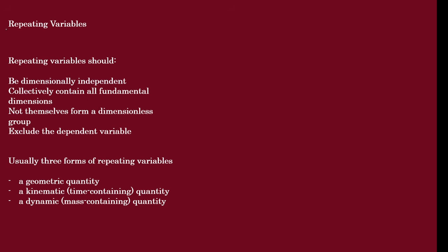And now we're going to look at the last important thing before we're capable of solving Buckingham Pi problems. And that's the concept of repeating variables. In some literature, you may see them being referred to as scaling variables. Okay? So a scaling variable is a variable chosen to be repeated across the other non-scaling variables to create the pi terms. What does this mean?